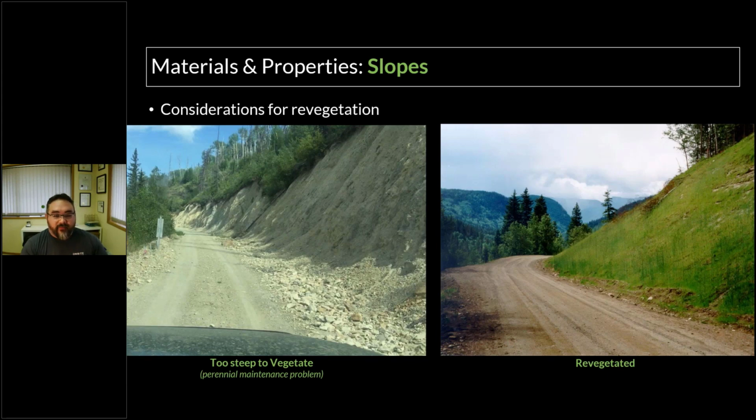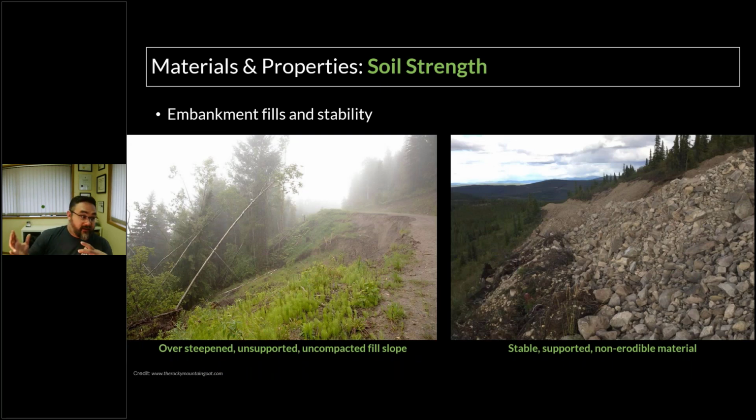On the other side, and in the same way, when we're thinking about soil strength or stability on the fill side, we have to understand the materials that we have so we can understand how they will behave and how strong they are for how much fill we can put down. So in the example above, obviously some finer material, uncompacted fills, probably overly steep, versus, likely on approximately the same side slope, a rock fill that's made of non-erodible material that's keyed into a bench.